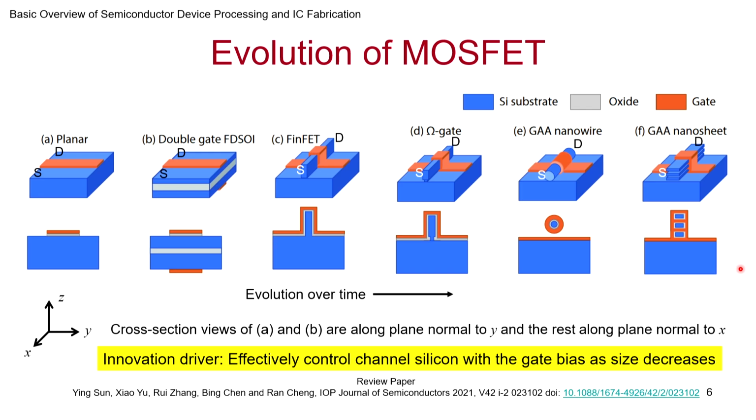Now this, it turns out, is not enough. It is because Moore's law requires that functionality keeps increasing. So one of the tricks that people have used is, instead of using one transistor, can we have multiple transistors? So the initiation has been made. Now this is not something new. People have thought about stacking transistors in 3 dimensions for a long time, but it brings with it a lot of challenges, as we will see in the next slide.